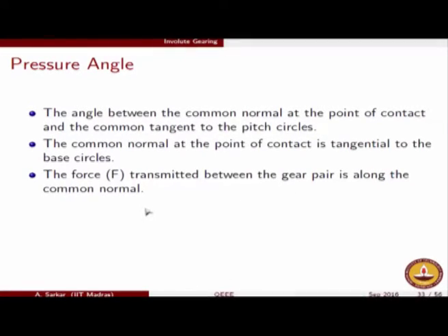That is very important because, as Ujjwal Rane said, it is a positive drive. There will be a force transmitted from the driver to the driven, and assuming the contact is frictionless, because we are not accounting for any dissipation mechanisms within our gears, the force will be transmitted exactly along the normal direction.